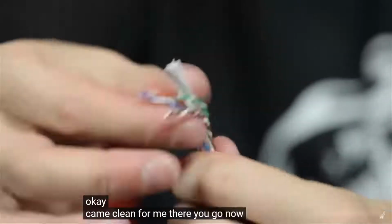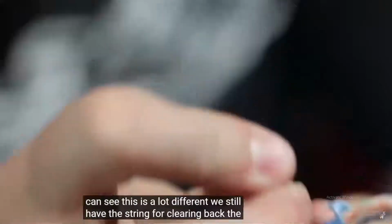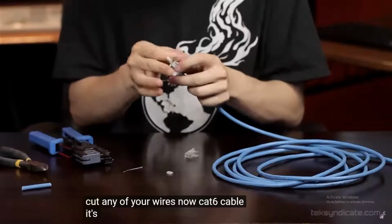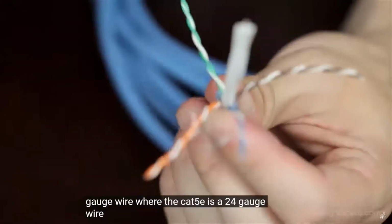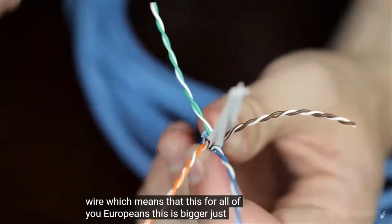Look at that. Came clean apart. There you go. Now, you can see this is a lot different. We still have the string for tearing back the sheath. We don't need it. Careful not to cut any of your wires. Now, Cat6 cable has got a larger conductor. This is a 22 gauge wire, where the Cat5e is a 24 gauge wire. Which means that this, for all of you Europeans, this is bigger. Just a little bit, but it's bigger.